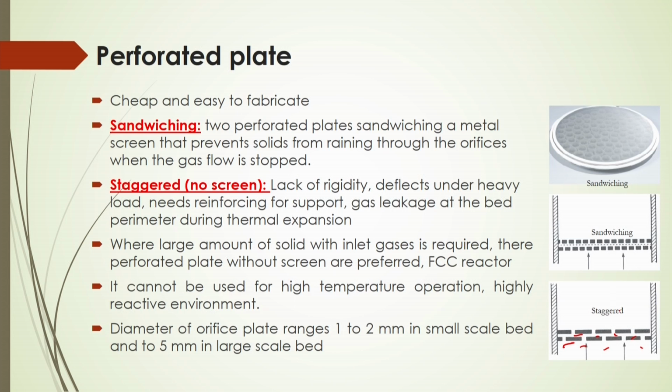Where a large amount of solid with inlet gases is required, perforated plates without a screen are generally preferred, like in an FCC reactor. This perforated plate cannot be used for high temperature operation, and also it cannot be used in a highly reactive environment.